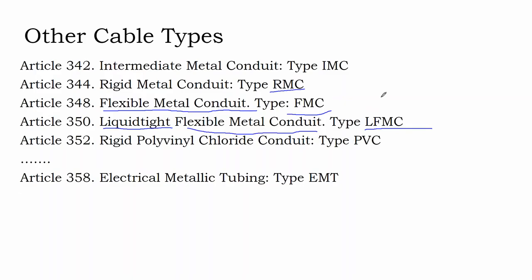And that's pretty useful because it's metal, and so A, DC wiring, solar cable has to be in metal when inside a building. B, it's flexible, and so sometimes the end runs of your conduit, having that flexibility is useful, or being able to run it through an attic can be useful.